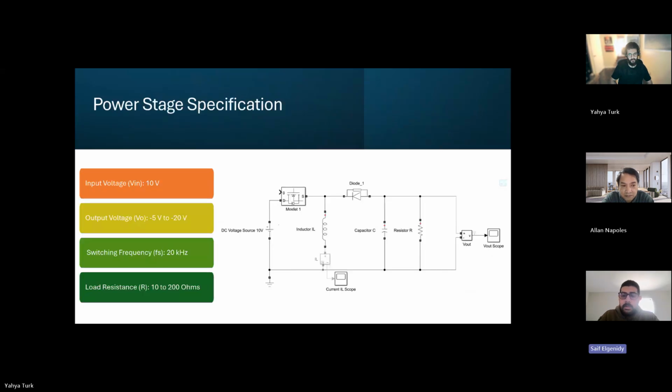And here to look at the circuit topology, we can see that the input voltage source provides energy to the converter, in our case, which is the battery supply. Next is the inductor, which temporarily stores energy in its magnetic field. The current flows through it and releases that energy to the output when the switch is turned off. The MOSFET switch is the switch element. It turns on and off rapidly, controls the inductor, it stores energy, and then transfers it to the output.